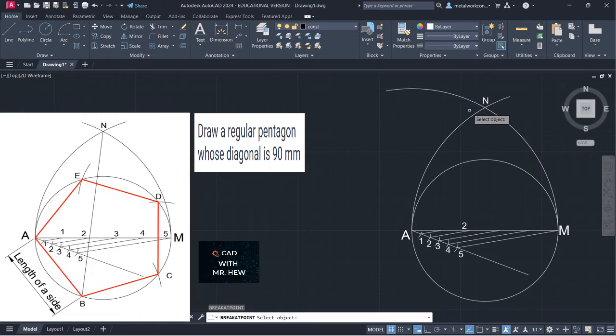So we're gonna check now. See? Look at this one. This is one line. If you come here now, this is now 2 arcs. Right? So I can press delete and get rid of it. All right? Good. Now the next step is to draw a line from N. So I'm gonna turn on object snap because I turned it off. From N intersection going through 2. Right here. Enter.